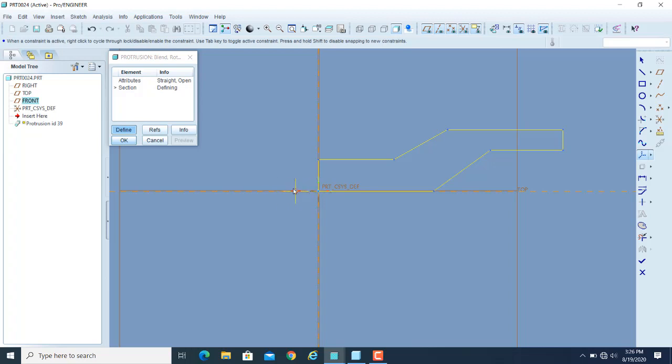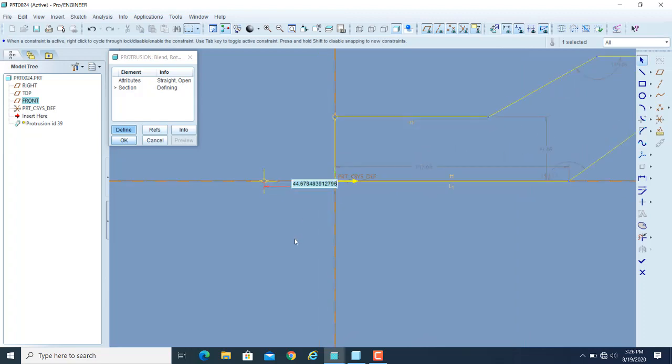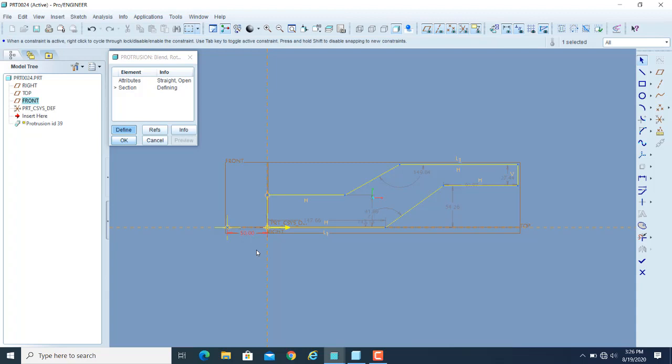And suppose I give some offset distance of the axis from the original entity edge. So suppose I define it here. Once you define that, you can also set the offset distance in between your axis and the entity. So suppose it is, let us say, 50 units. Yeah? So now we will have that 50 units of hollow space or hole, you can say, in that revolved object.